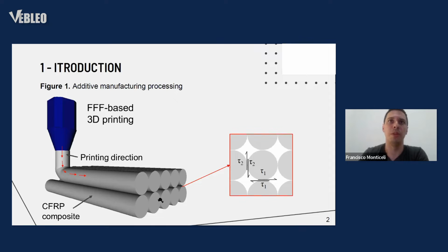This porosity is detrimental to mechanical performance, even being a suitable way to perform fluid transport, but for structural application it is not so good because we have a limited interaction area between the filaments, which decreases the shear in all directions, and delamination is more prone in these regions. So the mechanical behavior of these components is too low for structural application.